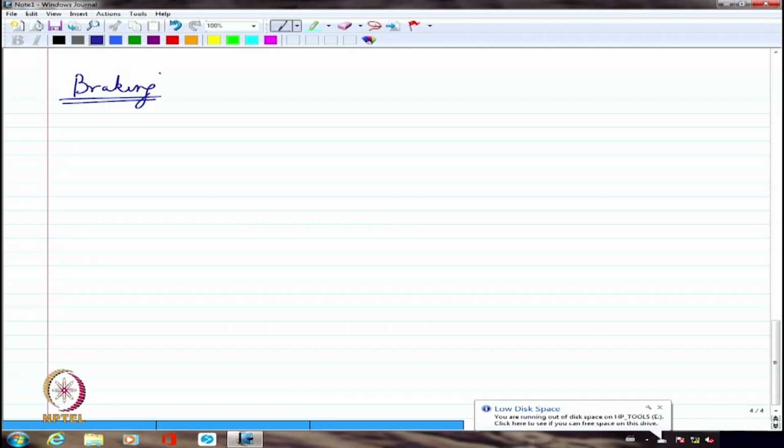Let the back EMF be there. How does it matter? Why would it spark? Okay, so you put a diode. The diode will take care of the current.